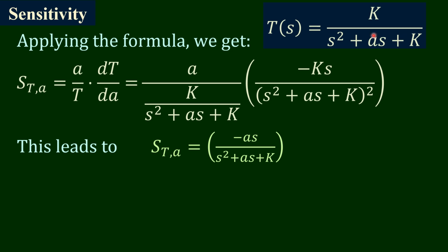So in the design problem, if we want to design a less sensitive system, this means we have to choose a large value of K. But again, there is a trade-off: in the closed loop, in many situations, whenever we increase the gain K, the closed loop becomes an underdamped oscillatory system, and in many cases it may become unstable.